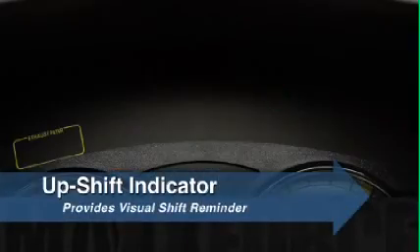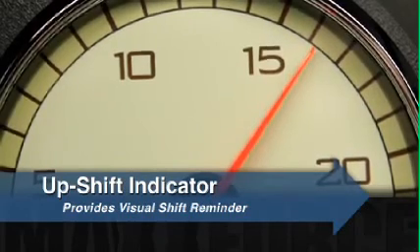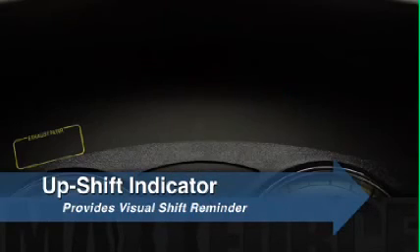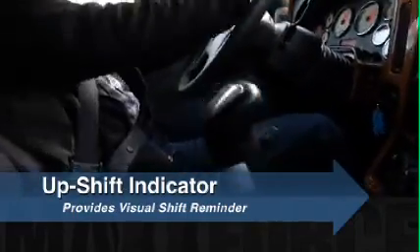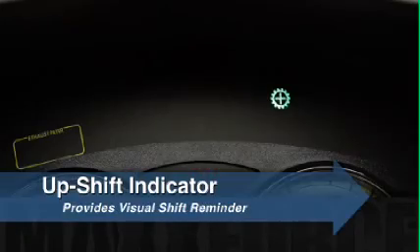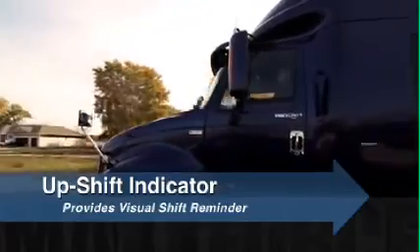The Upshift indicator feature provides a visual display to the driver that the transmission should be shifted into a higher gear. The signal is important when utilized with progressive shifting to promote earlier upshifting to drive within the optimum fuel economy range. The Upshift indicator is especially useful because it varies based on load conditions to indicate the perfect shift points.